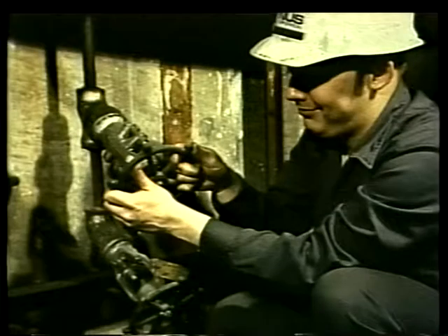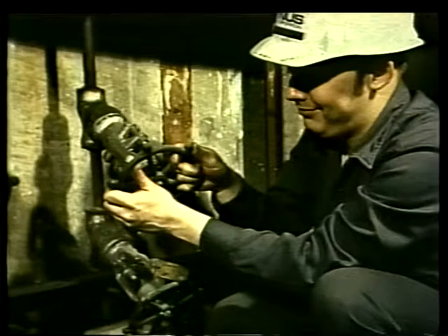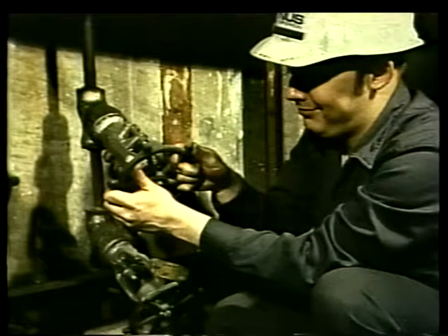Open the drain valve. The drain valve is not always located right at the bottom of the gauge, but can be found by following the drain pipe at the gauge's bottom. Opening the drain valve should drain and depressurize the gauge. If it doesn't drain quickly, it may mean that the drain is blocked and still under pressure. Do not continue disassembling a gauge that you think may be pressurized. Doing that could be extremely dangerous.